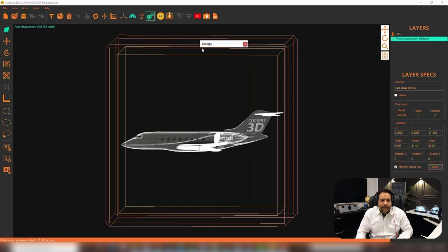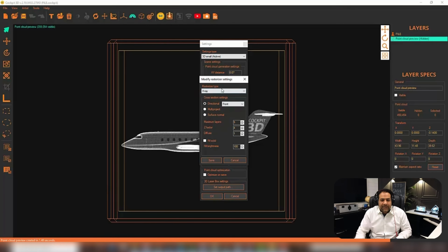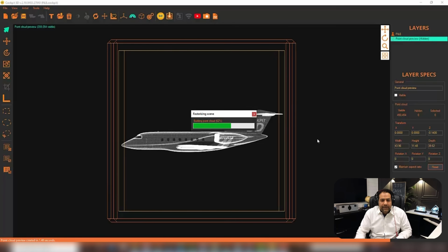Okay, now, I was talking about how spherical objects might turn out better with a different casting. So multi-project changes the way in which it's projecting these points, looking at it from top to bottom, left to right, front to back, and essentially it looks at one or the other, and it makes a decision as to where to cast the points from. So I'm just going to select multi-project and see what it looks like.